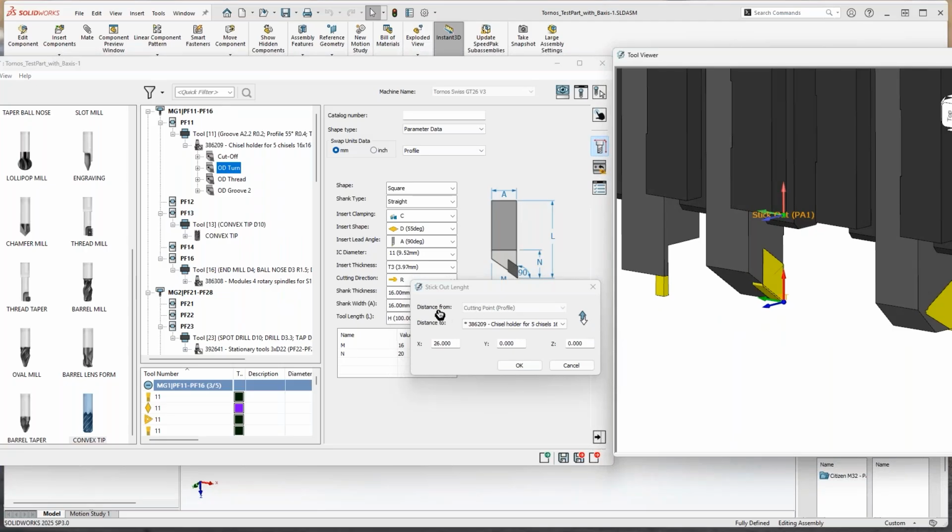And what we have here is we are calculating, or giving you the options to put, the distance from the cutting point, so from the cutting point here to the distance of the holder joint. Now you can do it also the opposite way. You can go from the joint towards the cutting point just by clicking on this icon over here. So basically these are two switches. It goes from this in the direction of X, Z, and Y towards this cutting point. You can see it with the red dot here, and you can put here the value. So you can see how nice this is.